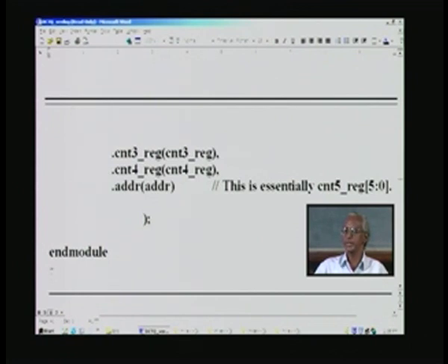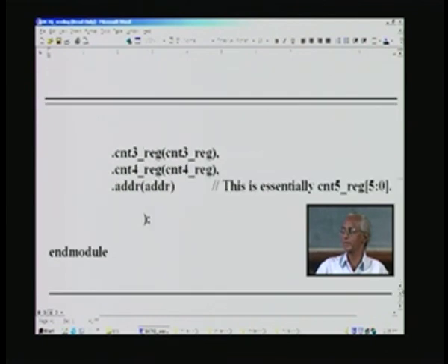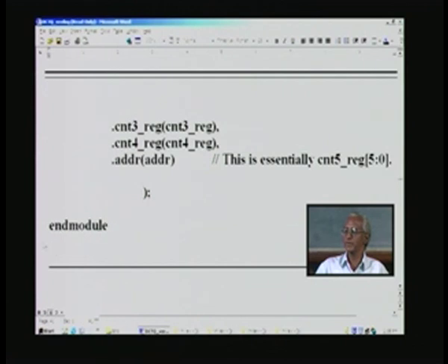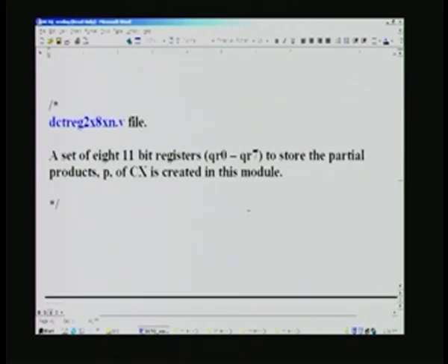There is no logic in the top design module. It is merely calling the different modules that you have seen here, everywhere just calling the modules, adder or multiplier as the case may be. And a good design practice, once again to reinforce the statement, is to avoid any logic on this. So, next we will consider some of the submodules which we have not seen before.